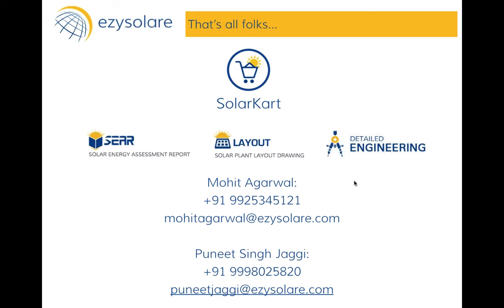So the wider the range, the more it is recommended for the MPPT range. Besides the MPPT range, we can talk about the MPPT numbers. If we have a single MPPT, then we can use only one string size in that inverter. But if we have a number of MPPTs, let's say two or three, we can have different sizes of string in that inverter. So we can have the flexibility of designing with multiple MPPTs.